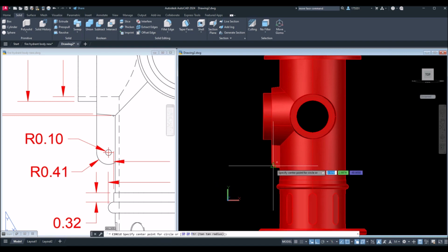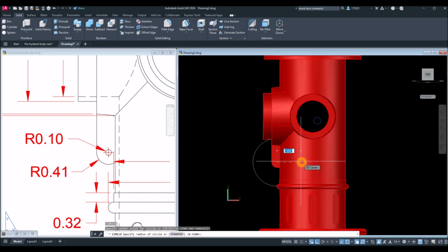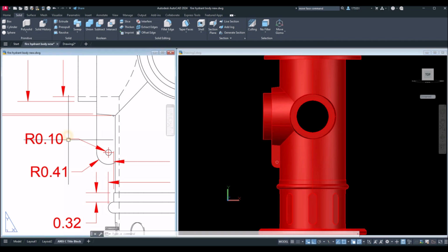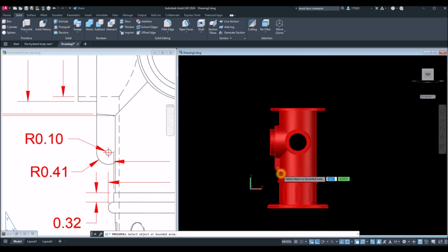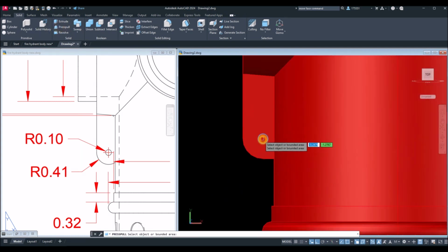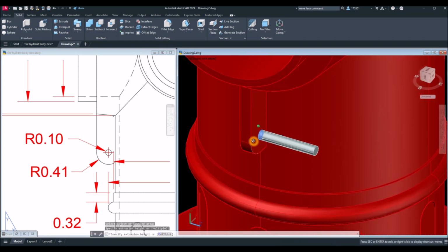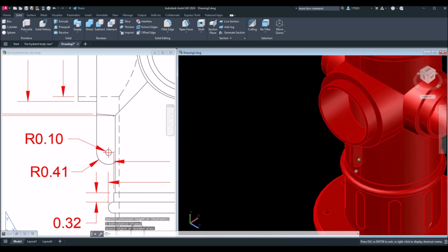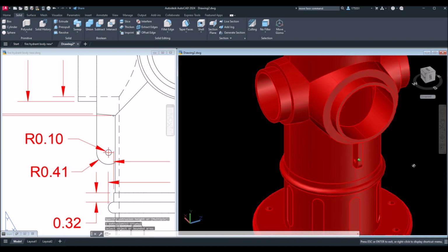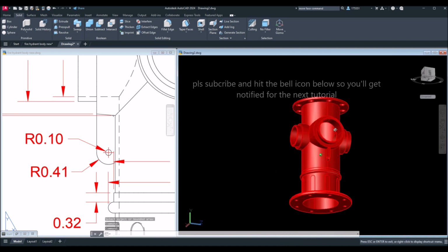So draw a circle, snap that center of that arc and enter 0.1 for radius, which is this one here. Alright, so now what I'm gonna do is use press pull command and just hover over that area. Once it turns blue, left click, let go and just push it up to here. Left click again. Okay, what else? And I think we're done for this tutorial.